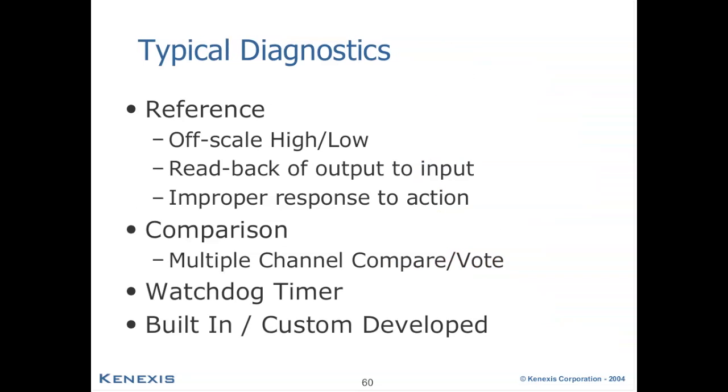Several means of diagnostics are available and vary with your instrumentation. The device may, for instance, use a reference target to detect abnormal conditions and move the system to a safe state, such as reading an off-scale high or low signal or taking the reading from the output and using that within the input. The device may also detect, for instance, an incorrect response during a desired action.